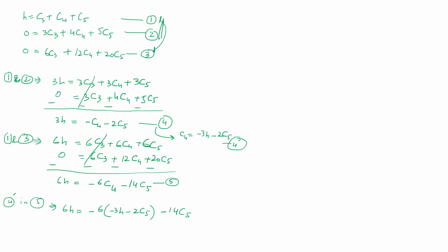minus 14c5. And this would obviously mean that you can solve this expression for c5, because this is the only unknown in it. H is a parameter under your control. You as a designer can specify the value of the rise, so this is controlled by H, so you need not worry about that. You only have got this coefficient to take care of.